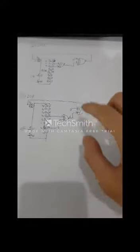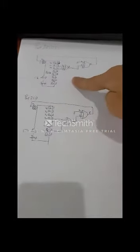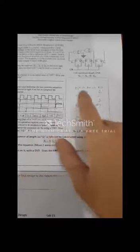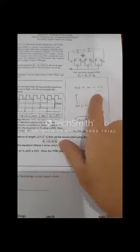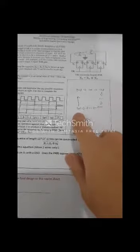Hi guys, so now I will be showing you Lab 4 Part 2. In this part, we will be using two schematic diagrams. One is for the 3-bit LFSR and one is for the 7-bit LFSR. As you can see here, this is the output that we have predicted, and it should run from 010 to 101, then to 110, 111, then to 011 and 001, and then to 100, and then back to 010.